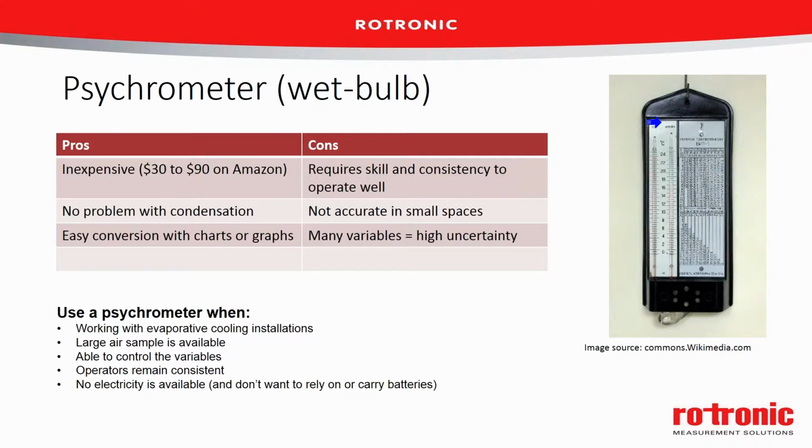Any variation in the airspeed over the sensors can cause the wet bulb temperature to vary. Too fast a speed and you'll get extra evaporation, causing the wet bulb temperature to go down farther than it actually should. If you're too slow, you get a little microenvironment created, and then your evaporation rate is too slow.